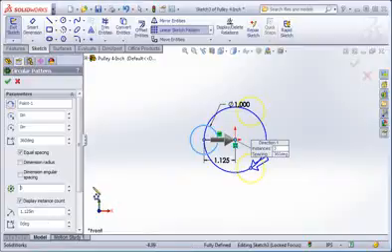based on an angle. I recommend that if you use sketch patterns, you control the center of the pattern using sketch geometry and dimensions. You'll find that this is a more direct method of controlling the center of the array, and it will be easier to edit if you do this. Once you've applied these settings, type the Enter key to add the pattern.